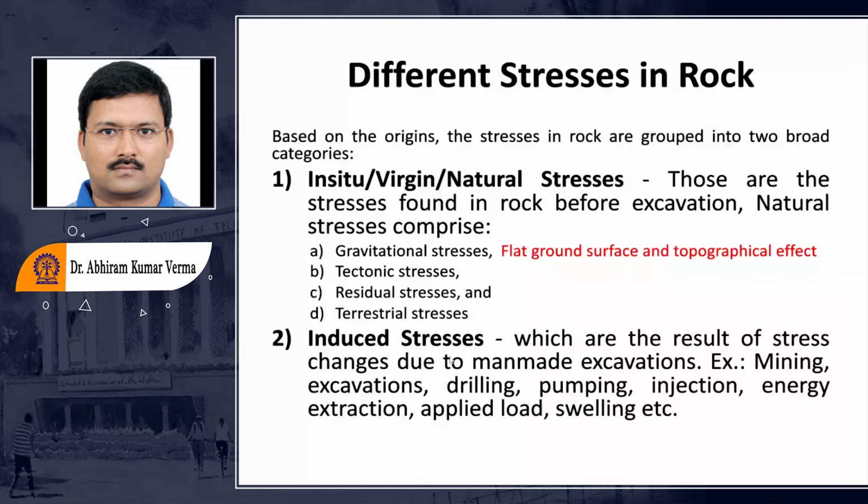And next is your induced stress. When I'm making any man-made excavations, maybe mining, drilling, pumping, injection, energy extraction, applied load, swelling, any sort of excavation in the rock mass, it is going to add or reduce the stresses around that particular point. So that will be called the induced stress. We will come to that, and we will have a detailed study on this.